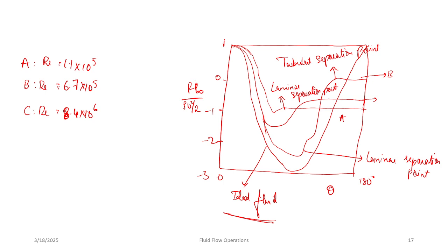It has a bit of right and left symmetry about the center line at right angles to the flow. So if you integrate this equation, you'll get the pressure force as 0 because of the left and right symmetry. That is, there will be no force acting on the cylinder. This is contrary to the actual flow. When we have a real fluid, the resultant force will not be zero.